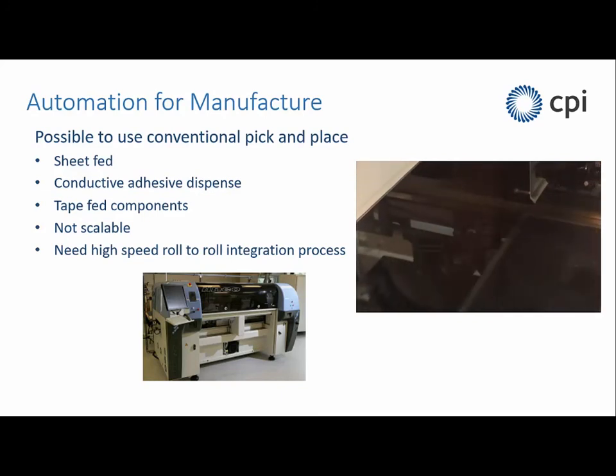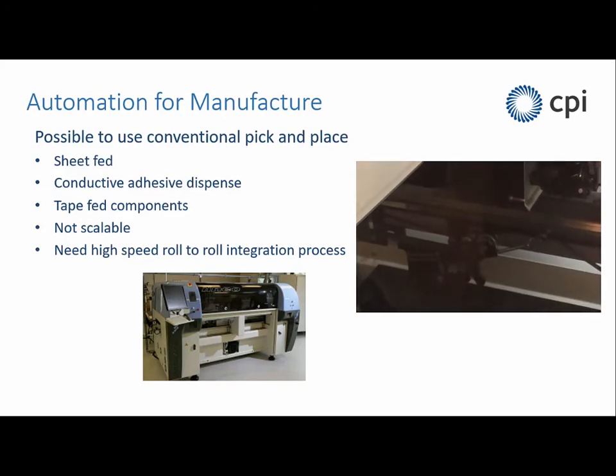So that video shows the assembly of LEDs onto a flex substrate using a conventional PCB machine. Okay, so if you've got Europlacer type equipment that can do PCB assembly, you simply need to mount your flex circuit onto a rigid carrier, and you can do assembly just as you do for PCBs.